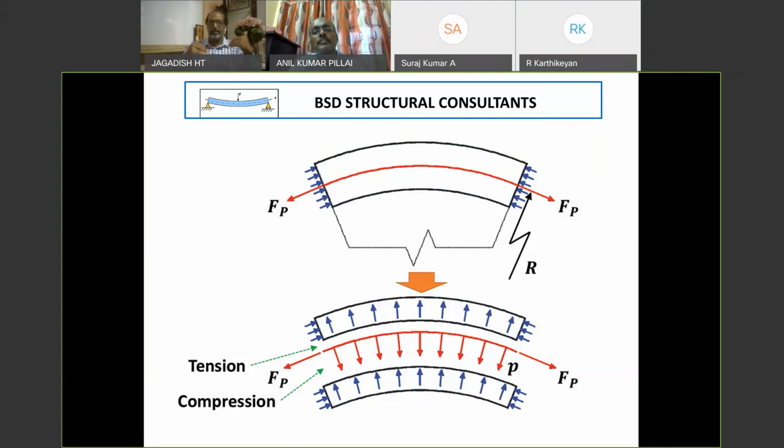Whereas in the re-engineered dome, reinforcement also was made orthogonal. By doing so, we were able to put reinforcement below and above the cable. And this reinforcement, top and bottom mat, was tied with radial ties. By tying the bottom and top mat, we were able to achieve whatever is shown here, the radial tension was taken care of by the reinforcement.